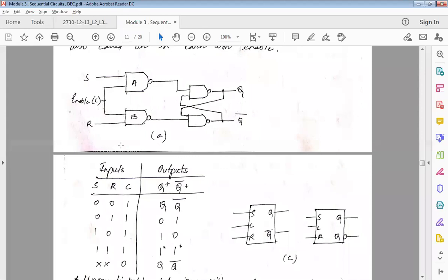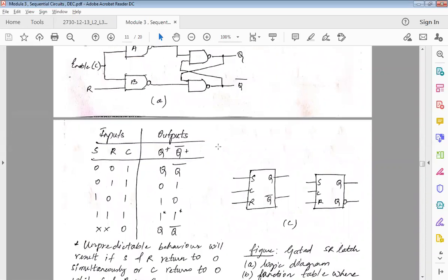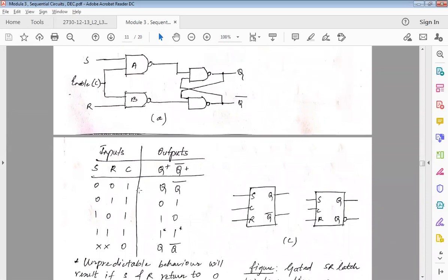So that's the reason I'm using an AND gate and a bubble. So NAND gate, fine. Similarly, you can see that whenever there is 0 for your enable signal, it means that your S and R are don't care. Why is it don't care? Because it doesn't matter whatever values you give, because it is disabled. So the values that are going to stay are going to be your memory values. Q and Q bar are nothing but the previous state outputs.